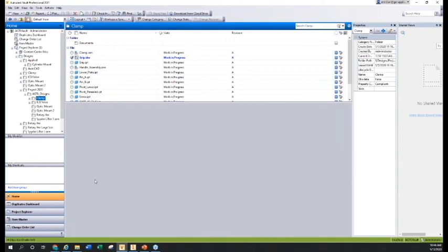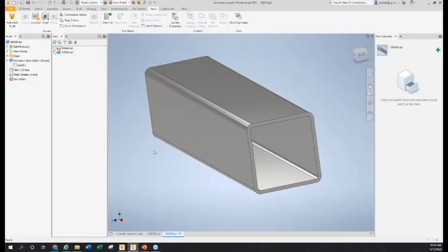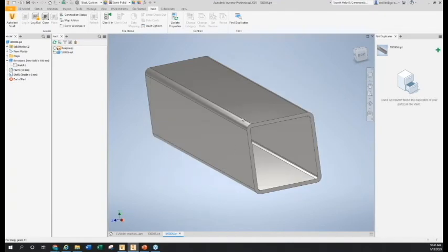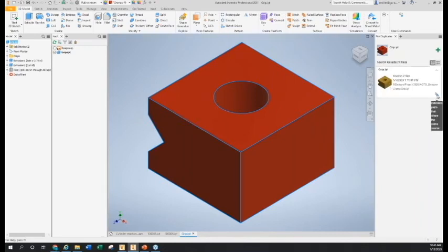And one of the things I wanted to point out, there is an indicator if the part file originated from the exact same part. Basically, if they're identical, that's another indicator that you see within Inventor. Like if I open up the grip here, I think that's one, and if I do a search on the grip part, hit search. The indicator is at the bottom right of that one. So it did find one out there.